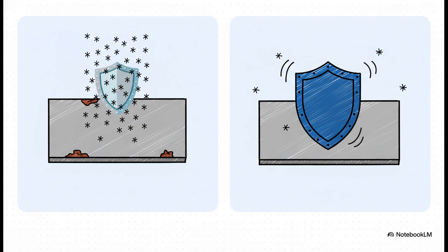A standard stainless steel is great for a lot of things, but that passive film can be broken down by chlorides, think salt water. So for a really aggressive environment, you might need to step up to a high-performance alloy like Hastelloy. Its armor stays strong under much harsher conditions. If you choose the wrong material for the job, you're basically designing it to fail from day one.